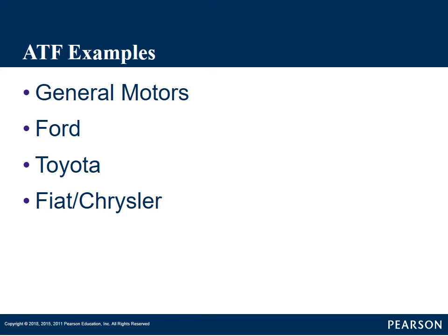When they came out with the ATF 4, they recommended changing everything that had ATF plus 3 to ATF plus 4. So if you brought a vehicle in with ATF plus 3 and you needed to service it or do a fluid exchange, a fluid flush, you would do it with ATF plus 4. Those are just kind of some different examples. There's a lot of different transmission fluid out there. You want to make sure that you put the right fluid in with the right transmission.